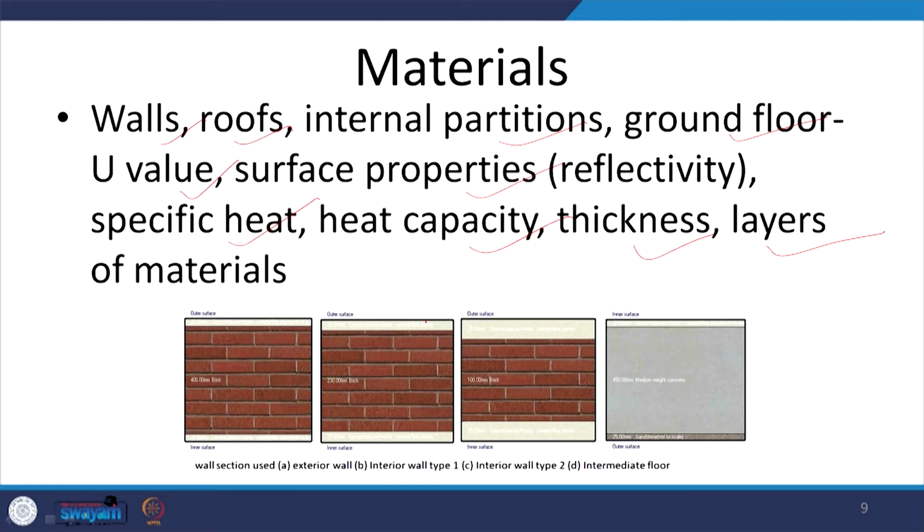So, this is the regular brick wall, which is a 230 mm thick brick wall with 25 mm of internal plaster and 25 mm of external plaster added to it. Software like DesignBuilder, and almost all others, already have the thermal properties of these individual materials built into the software. Here it is for concrete.